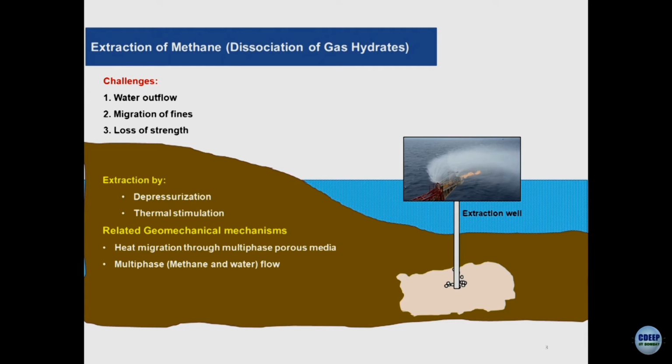If the fines get washed out from a sediment, what is going to happen? The voids or the cavities will get created, and the chances are that the bearing capacity of the system is going to decrease. Hydraulic conductivity is going to increase, gas permeability is going to increase, and so on. So, look, the whole of geomechanics is now changing. In the conventional geomechanics, you thought that everything is constant volume, inflow is equal to outflow, all the time you derived this, your control volume never deformed. Here we have all challenges.